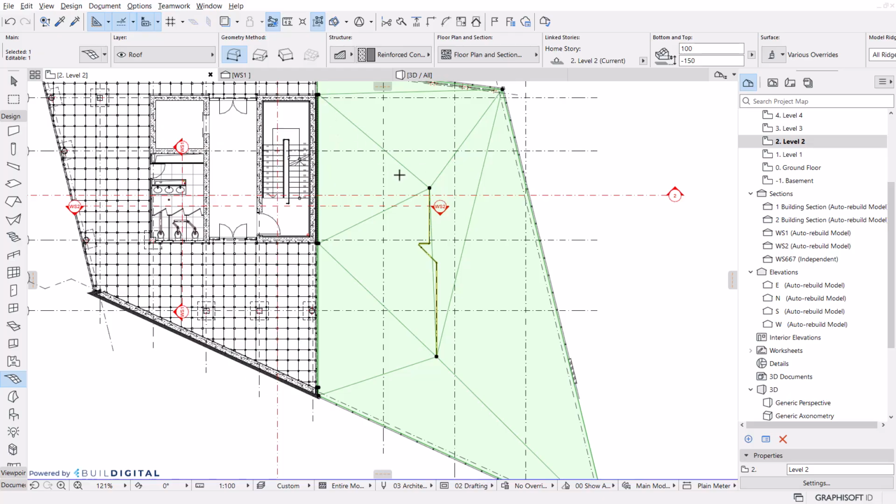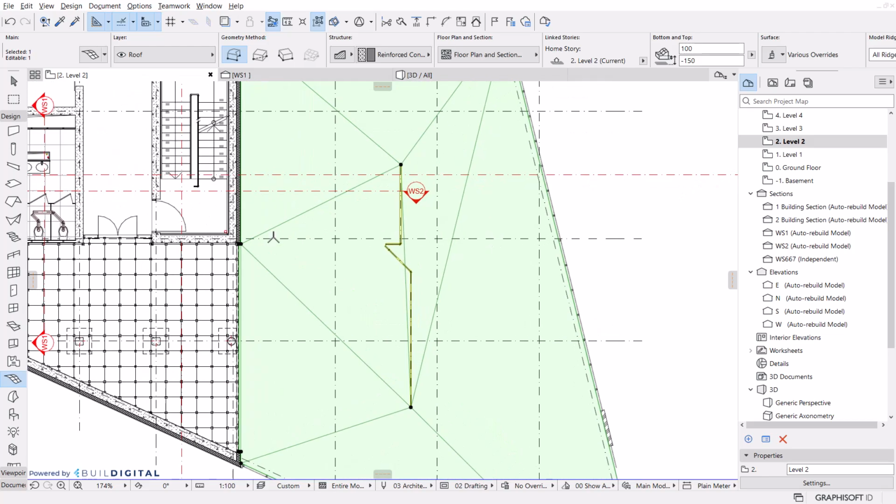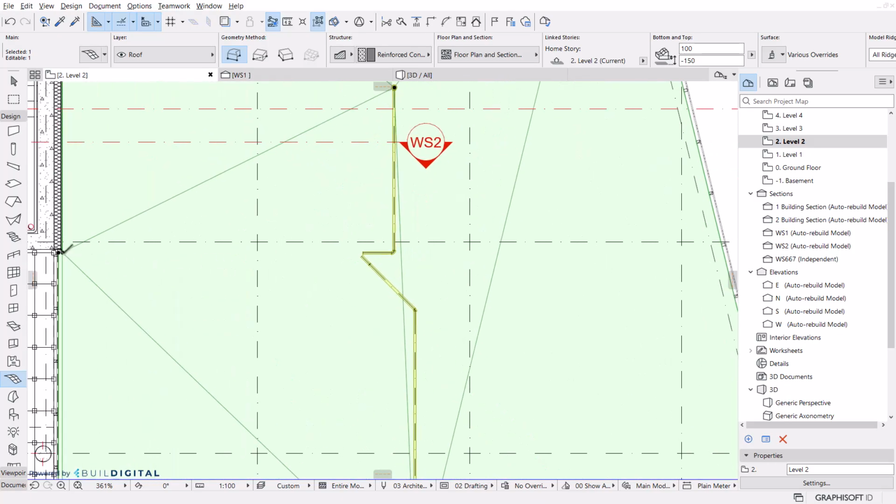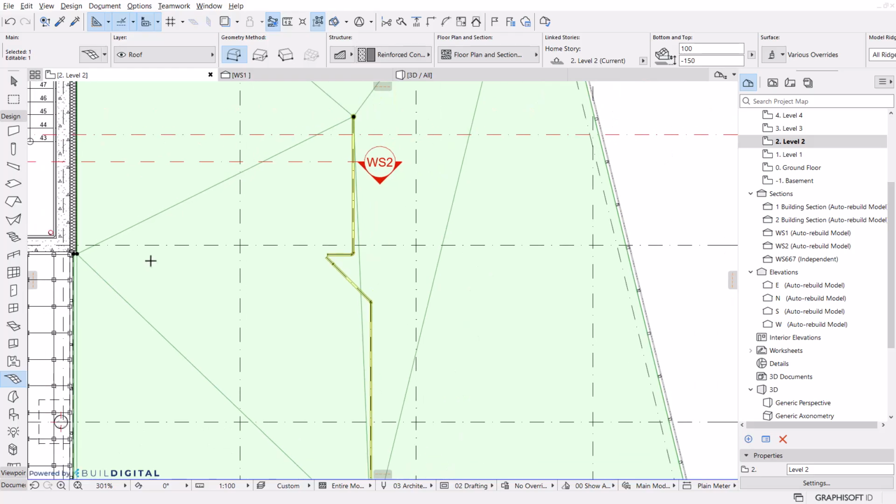And you can see how the mesh itself started creating the drainage, the ridges of the planes that are draining down. Now, what we should do is split this in two areas. So you have one area here in the middle that drains to this point right here, and one above that drains to that point there. Let's use, for now, the fact that we have a corner right there. So what I'm going to do is use a temporary guideline and align that with that hotspot right there.